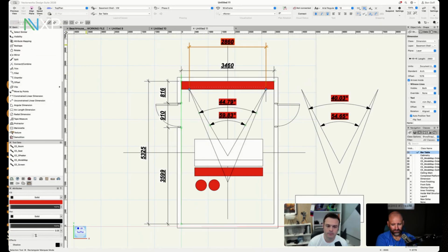So Johann's asked us, if you're doing waveforming, can you skip looking at the modes? Well, yes and no. There's a frequency region where waveforming is going to be really effective. Then there's a transition where its effectiveness starts to roll off, and then where it's just not trying to do anything. That depends on the spacing between subs and the room dimensions. There are some calculations to do to work out how high in frequency it will be effective.